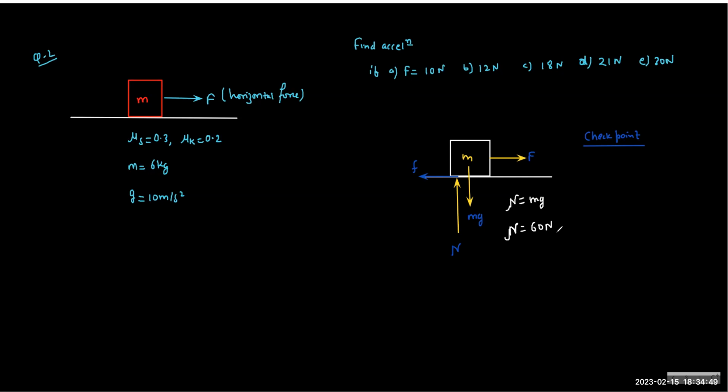Okay, all right. So what is Fs max? This Fs max is how much friction I can generate if required. So what is the maximum value I can generate? What is the limiting value I can have? And because normal is well defined, this is also well defined. And you simply substitute the value. And you know that I can develop up to 18 Newton of force. 18 Newton is something I can prevent motion with. If someone is trying to pull by 18 Newton or less, it will never start the motion at all.